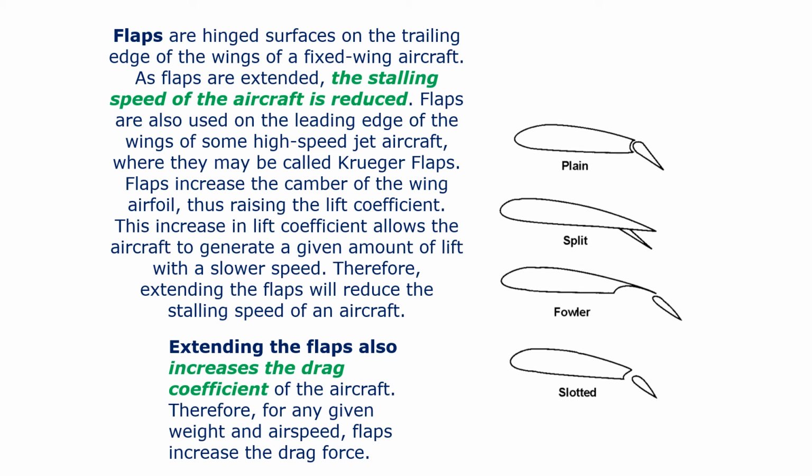This increase in lift coefficient allows the aircraft to generate more lift at a lower speed. Therefore, extending the flaps will reduce the stalling speed of the aircraft. Extending the flaps also increases the drag coefficient of an aircraft. Therefore, for any given weight and airspeed, flaps increase the drag force.